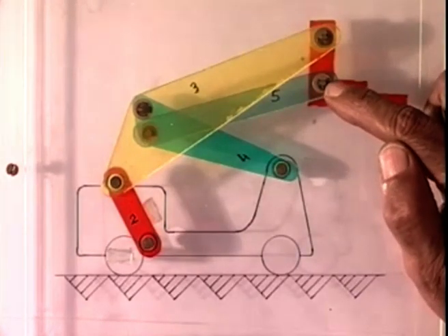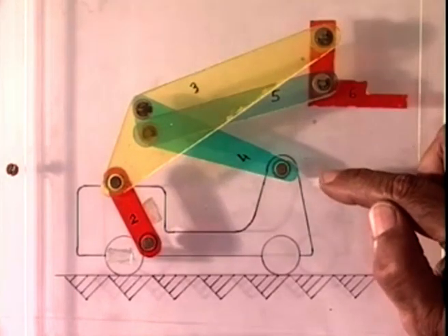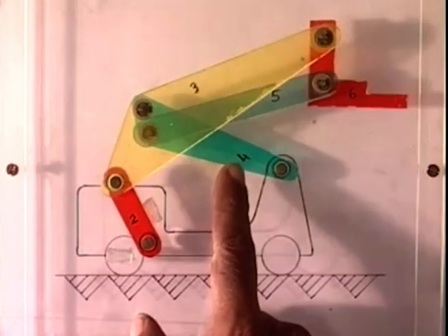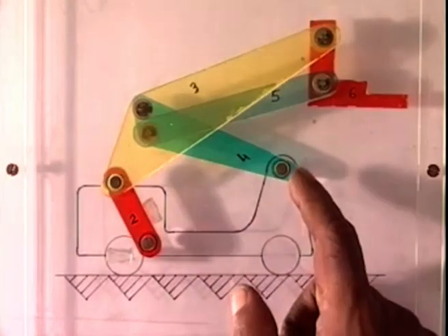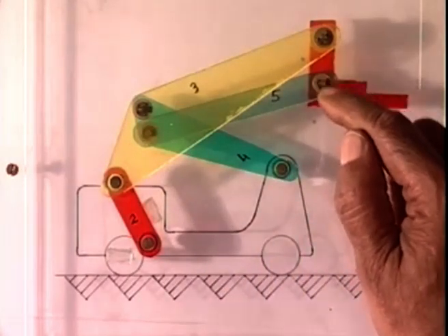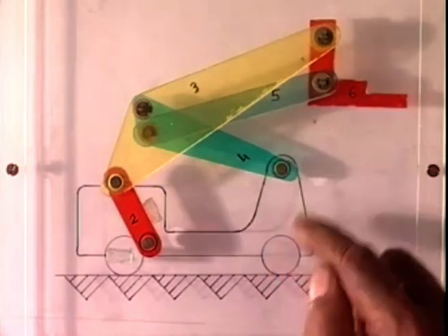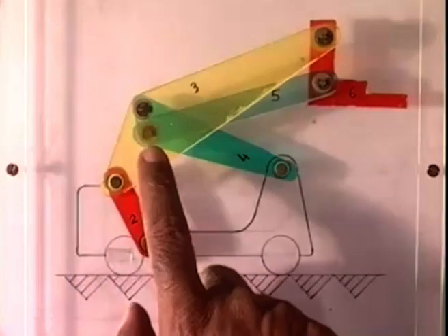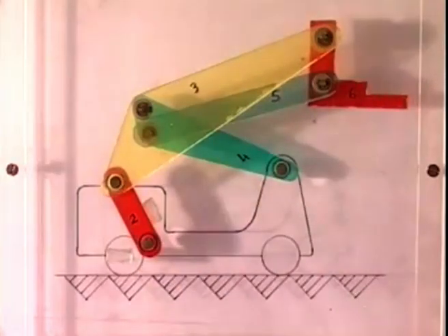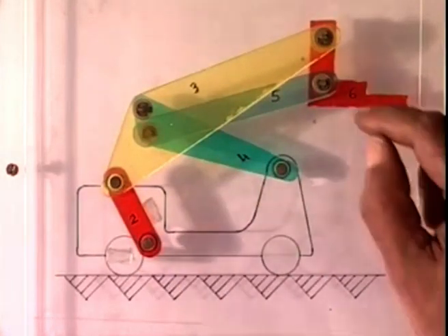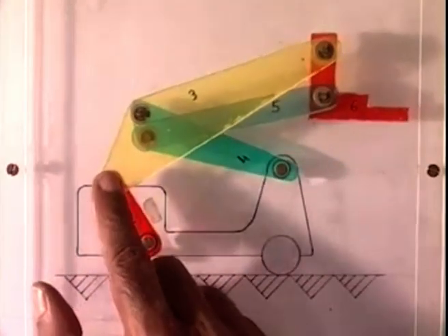After choosing this point D, we found the inverted positions of the D corresponding to the second and third configuration, holding this link, that is link number 4, fixed at its first configuration. And the center of the circle passing through these three inverted positions of D, namely D11, D21 and D31, I found the center of that circle at this point, which I called E. Finally, we get this 6-link mechanism where I have a fork lifter without any vertical guide.